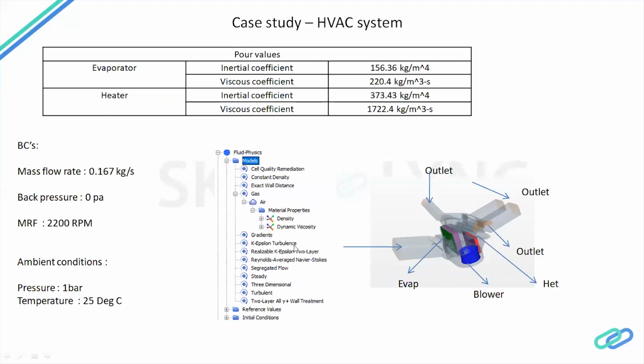When the Reynolds number keeps increasing beyond 2300 in pipe flows, it is called turbulent flow. So once turbulence has entered, we need to solve for the turbulence. So these are the turbulence equations, and this talks about a steady problem. Steady means the flow behavior is invariant with respect to time, and this is the number of dimensions. This is a 3-dimensional problem. We are going to solve in 3D. This is like boundary layer capturing. So this is the physics of how we set up the solver.